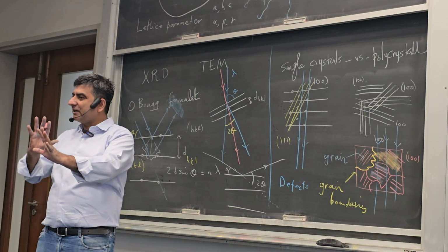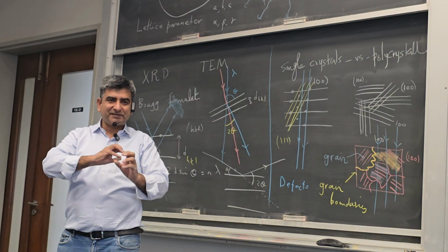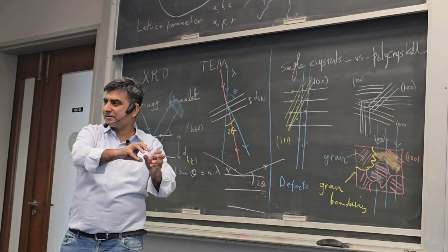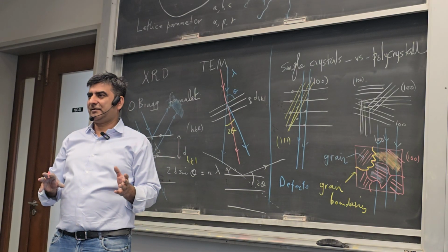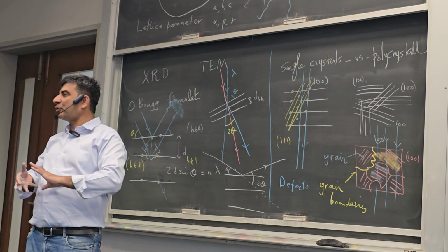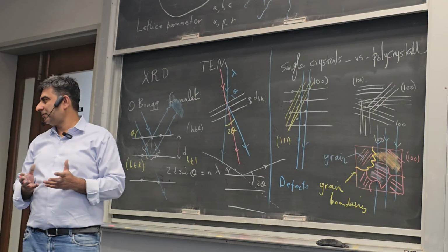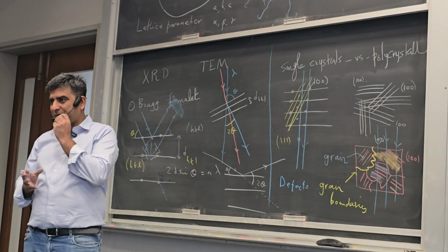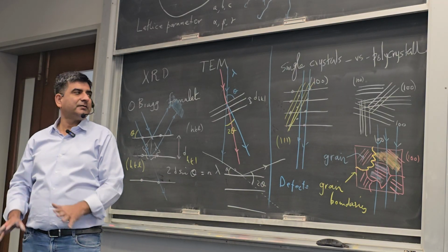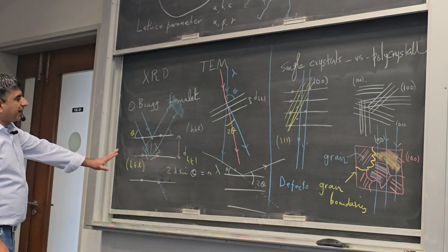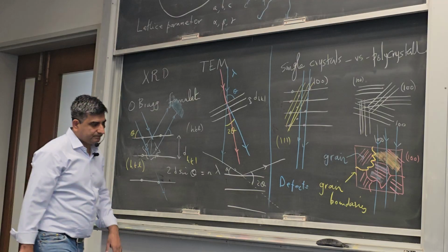Okay, so that's why the apparatus that is used to determine X-ray diffraction patterns from single crystals versus polycrystals or powders is different. In powders, you may not have to rotate the X-ray direction or the sample or the specimen. You may rotate it for other reasons, but that's besides the point. Okay, so now let's look at an example.